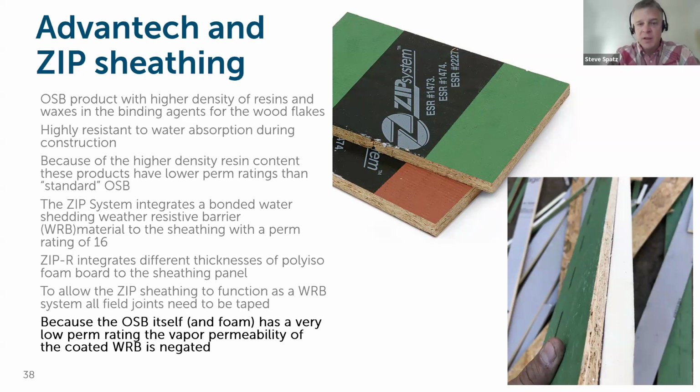But that also means that you effectively hit a vapor barrier in that material at the exterior of the building. The zip sheathing itself, the coating that is put on the zip sheathing as the vapor permeable WRB, has a perm rating of about 16. The OSB that it's bonded to is not the Advantech product, so it does have some permeability, but again, it's a very low vapor permeability, so typically under 1 for the substrate here.